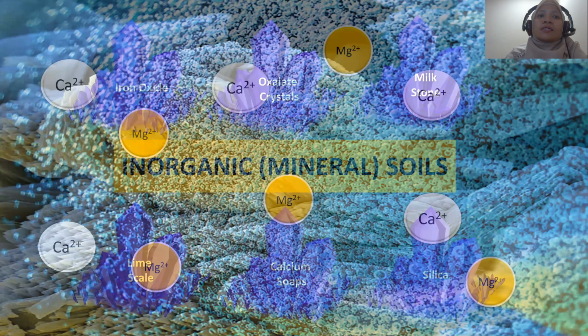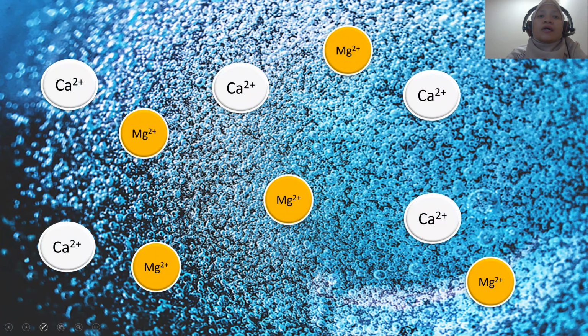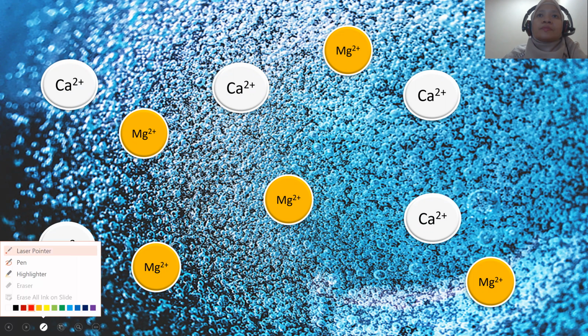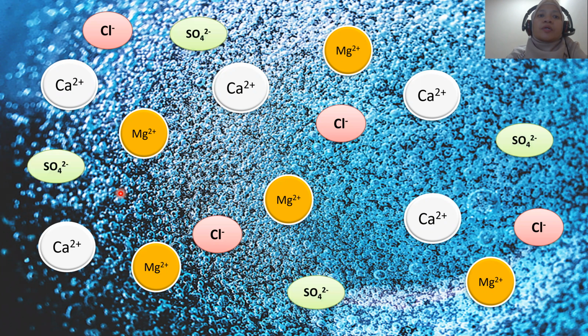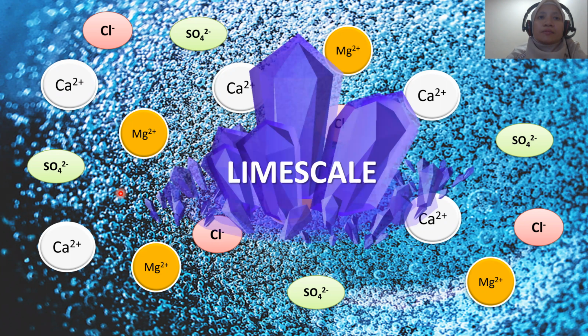Water is considered hard if it has a high concentration of dissolved minerals like calcium, magnesium, and these are main minerals that are often found in water supply. Besides that, dissolved fluoride and sulfate minerals may also contribute to hard water characteristics. The presence of these minerals can make significant problem because it can form limescale.